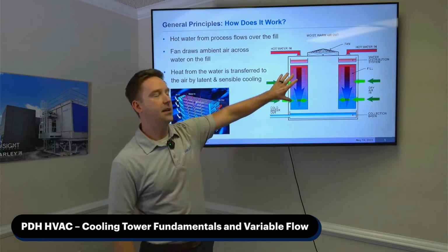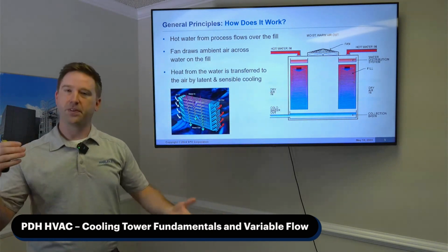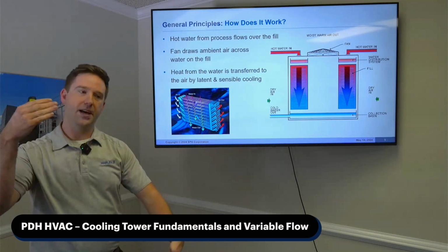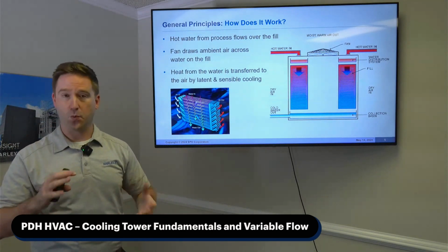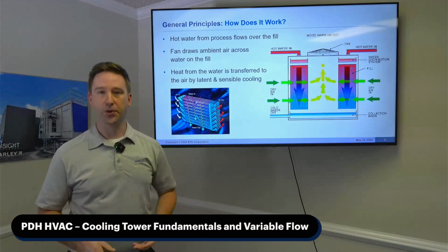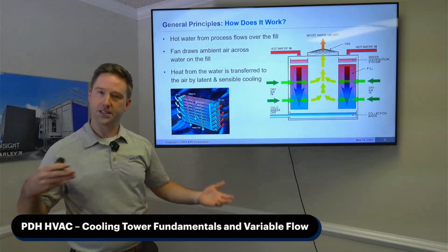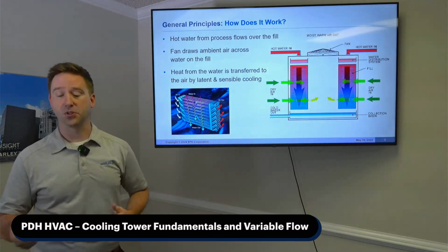You also have this heat transfer media, we call it fill. And so that fill is going to try and spread that water as thin as possible so you get as much air and water interaction, which will create that evaporation and that cooling. So again, simple process, but specific design, and it's designed to do it as efficiently as possible.